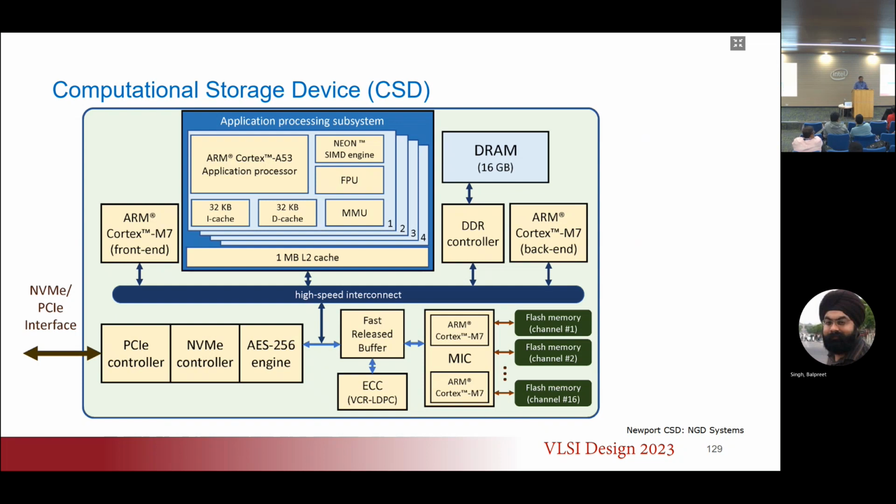So what would be my algorithm? Read one image at a time, bring it to the CPU, run the comparison, get the result, and just keep going. So if I have 1 terabyte of disk, I'd move 1 terabyte of data from my SSD to DRAM, and from my DRAM to SRAM, and do the computation. It's a huge amount of energy. So maybe we just don't want to do that.